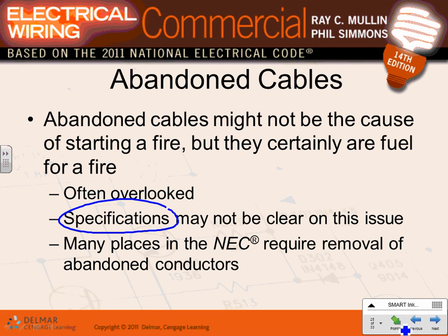Because people, if this is not to be used, they just leave it there. I want you to remove it. Because why? Anybody knows why? If this is not used, why do you want to remove it? You have to maintain a building, guys, for 50 years. Do you want the electrician to look here? They hire an electrician and say, oh, let's go fix that one or troubleshoot that one. It's not there. So it's confusing for the people who are going to maintain the equipment, right? Safety is related to maintenance of the equipment. If you can make maintaining the equipment easy, safety will be improved, right?